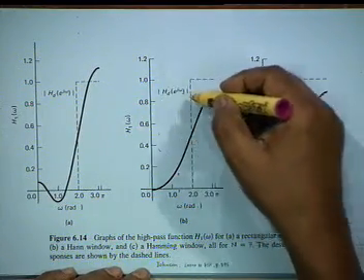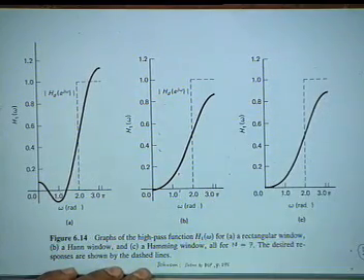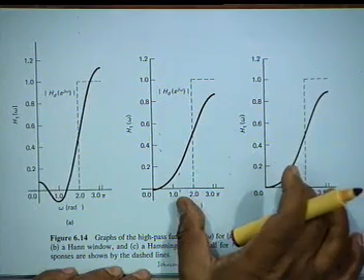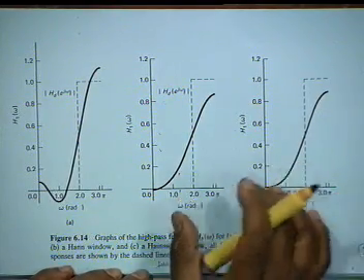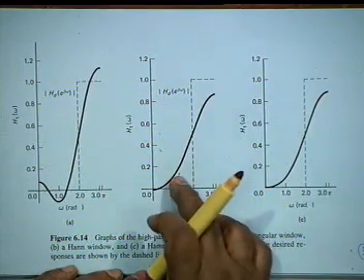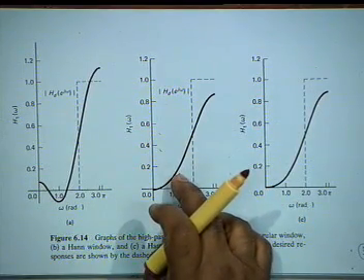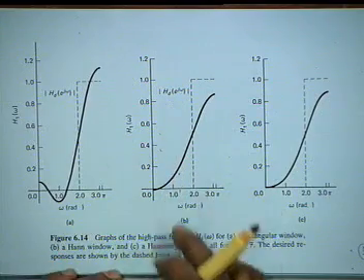The maximum response here does not go to 1, here also it does not go to 1. Notice that these two are close to each other, okay? They are close to each other because the windows have been tapered. But this Hann window will always give you a slightly inferior response because it uses a smaller length, okay?